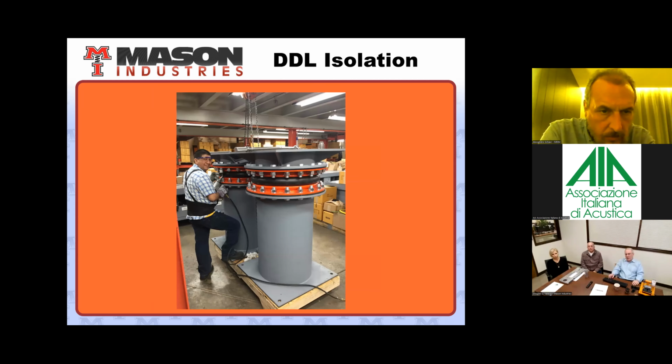They also have a role in scientific applications and industry. By increasing the area of the air spring, you can support higher and higher loads, just a function of pressure and area. And if you increase the volume of the air spring, as shown here, you can reduce the fundamental frequency. So these were built to support a large dynamometer at Ford Motor Company.